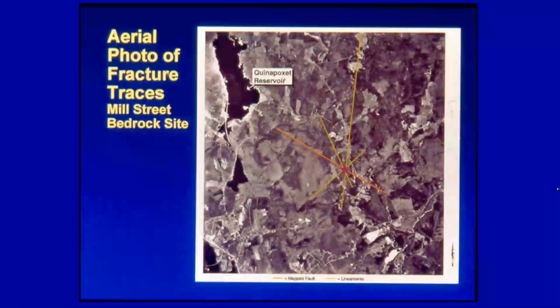This is advantageous because your odds of intercepting fractures that are going to yield water is increased, but also you are going to be able to induce recharge from multiple points of the compass. And plotting this up, it is obvious that drilling at this location right here is going to give a markedly higher likelihood for a favorable high yielding bedrock well than if you drilled at any of these points not in any way associated with the identified linear features.